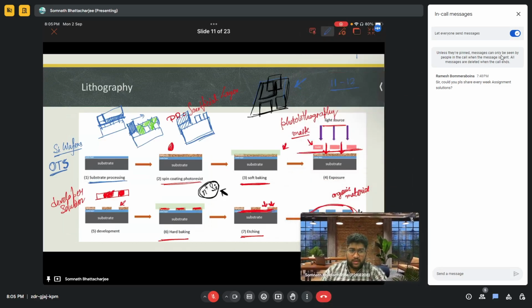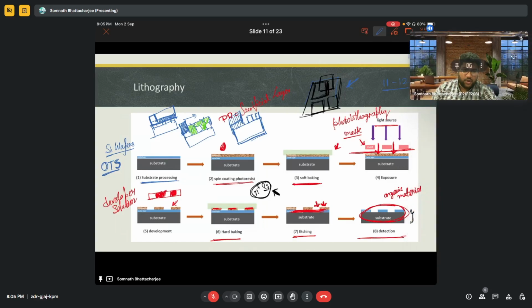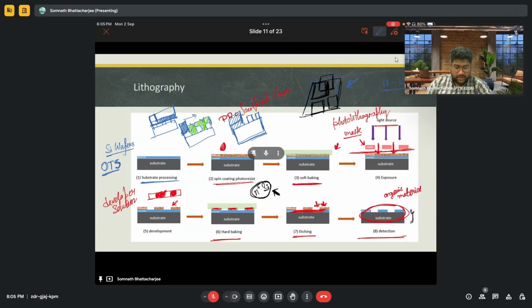And obviously even if you are etching 12 times, let's say the structure is like this, okay, and it is divided into 12 structures. Obviously the structures will be different for each level. What happens is that the lower level is etched always, right? For 12 times the lower level will be etched, so it should be stable to hold the whole structure on top of this. So these are the things you need to remember while optimizing a lithography process.